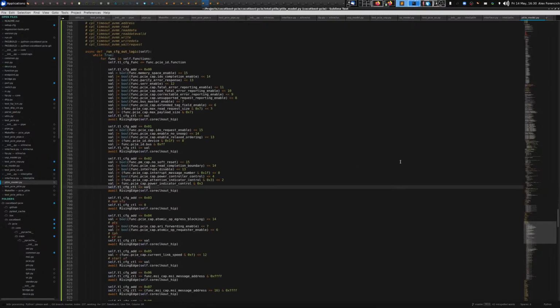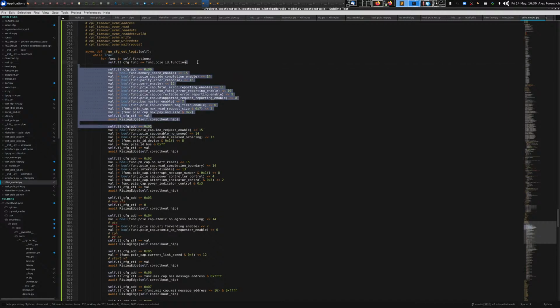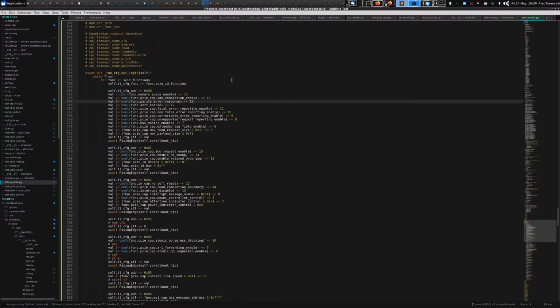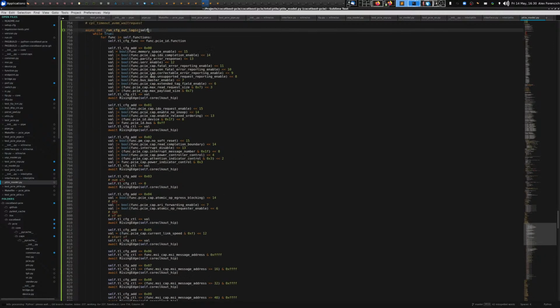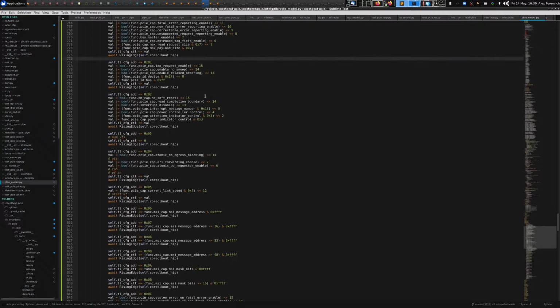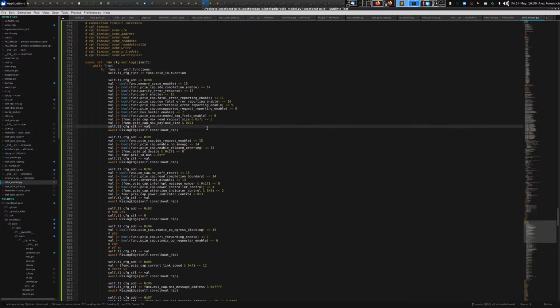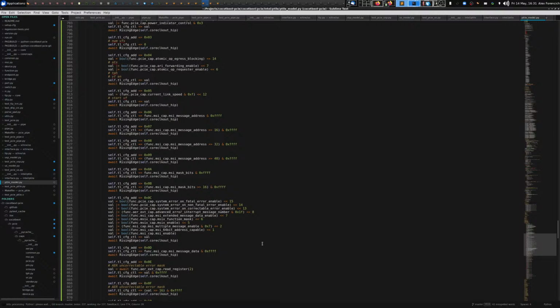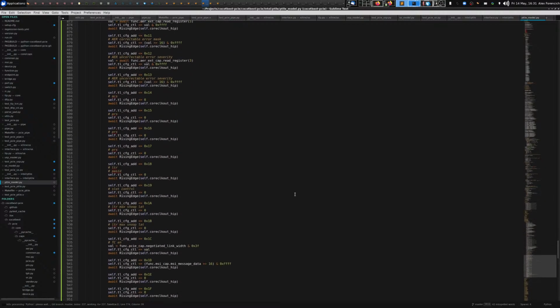There are some interesting design differences as well between some of the modules. Like the P-tile, it has a bunch of TDMA interfaces. Instead of providing a whole bunch of interfaces in parallel, this configuration output logic has one signal for the current function, one signal for an address, and then I think a 16-bit configuration output. It cycles through a whole bunch of different values, and the idea is you can look at the address and then latch in whatever value you're looking for. The advantage is it doesn't use very many pins. The disadvantage is that you might have to wait a while to get some of these values. But most of these don't change very often. Software might turn something on or turn something off, so if it takes a handful of clock cycles to update it, it's not really that big of a deal.